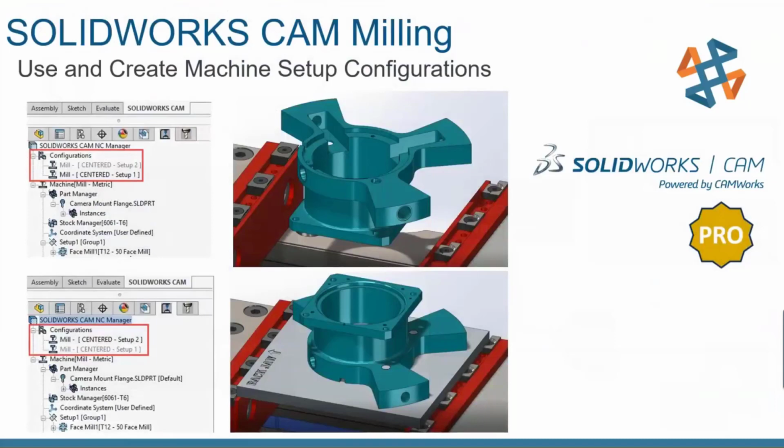We get into SOLIDWORKS, even if you don't need the two axis turning, SOLIDWORKS CAM Pro is nice because we can actually use assembly machining and program parts with fixture setups and also the machine setup that it's going to sit in. So then we can maybe machine one part and we can show the fixtures and tell it to void those fixtures, flip the part over. So we can take advantage of machine setup configurations in the assembly level, which is in SOLIDWORKS CAM Pro. Also, we can apply toolpaths to individual SOLIDWORKS part configurations as well. So if we have a family of parts of 5, we can apply toolpaths to each one of those configurations.